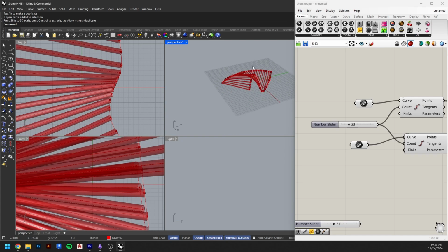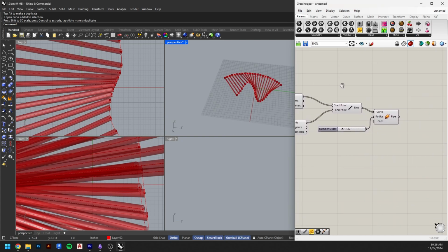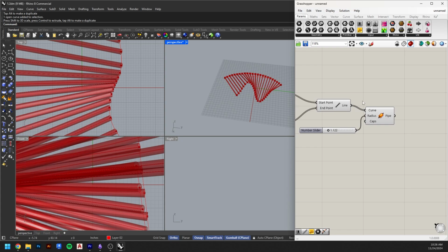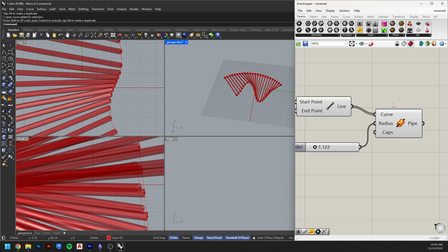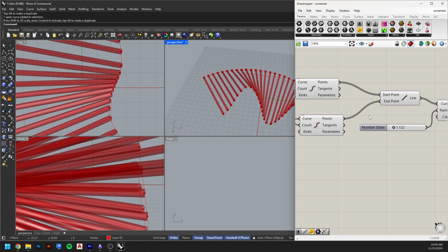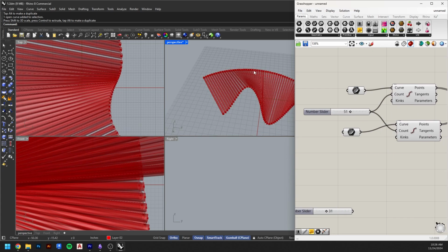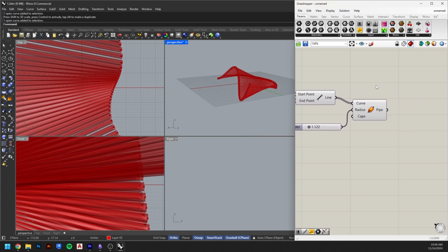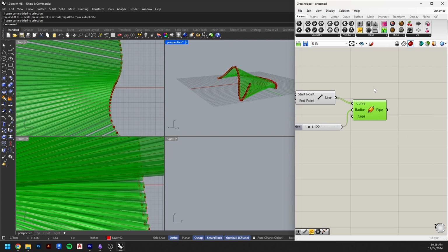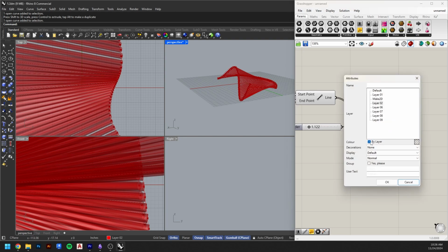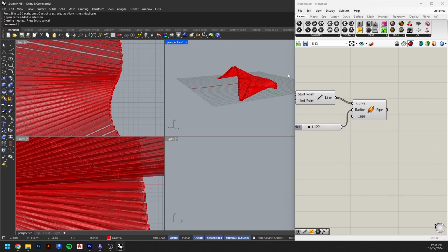And then when I'm finally done, when I'm finally ready for the end of the product, I want to say, okay, it is done. So now export, right? Export these items. And the word that Grasshopper uses for export is bake, like bake a cake. So I've decided, let's make it exactly the way I want. This is good. Perfect. That's how I like it. I want to now bake this. So I'm going to go to any node, you can bake at any point. So I'm going to go to my last one, and I'm going to right click on it, and I'm going to say bake. And it's actually going to say, these are some settings. How do you want to bake it? I'll say, yeah, okay.